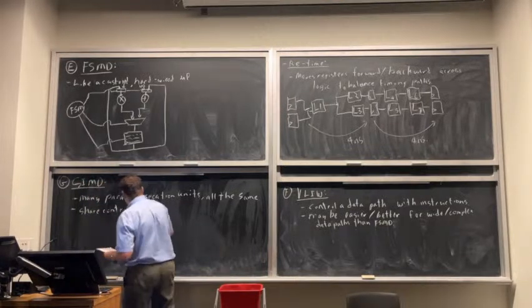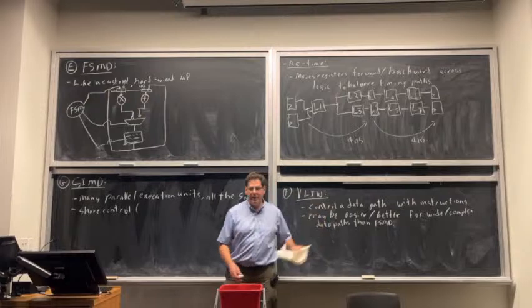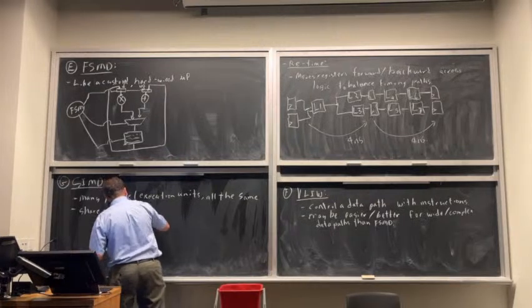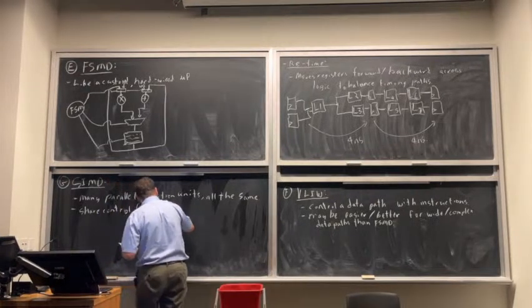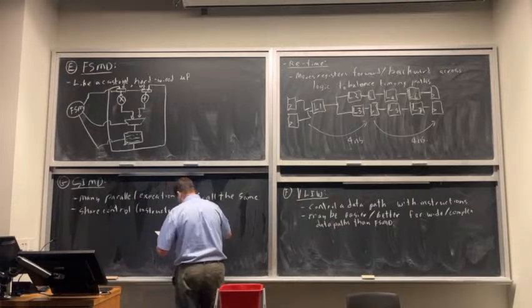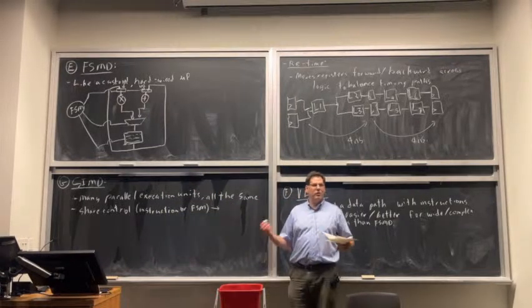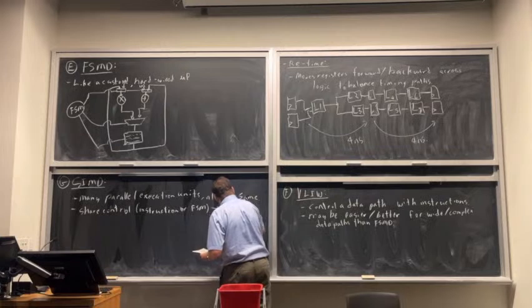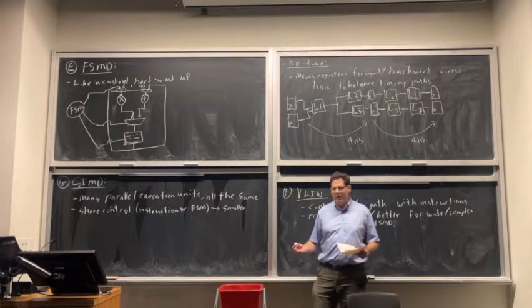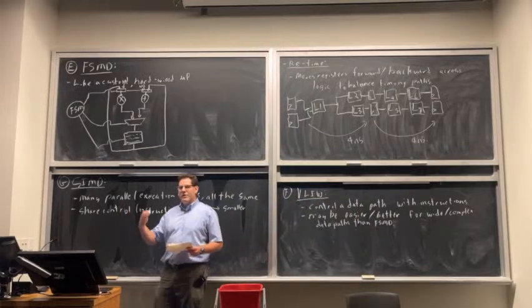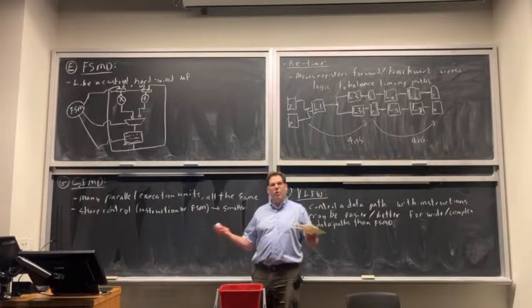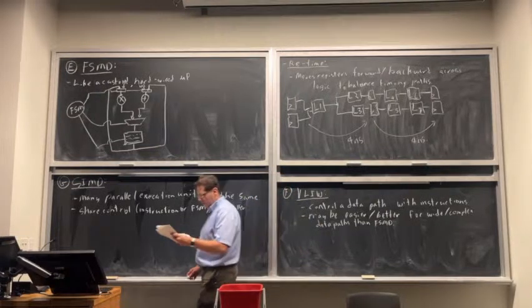Okay, so that control could be instructions, like we had here, or it could be a finite state machine, like we had there. And the reason to do this, well, it's just to amortize your control. It's smaller than having a whole bunch of independently controlled function units. So if it turns out that you tend to do the same thing on a lot of data, this amortizes your control. And your control is kind of overhead, right? It's not actually doing computations for you. It's just organizing the computation.